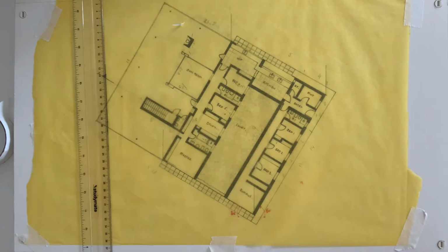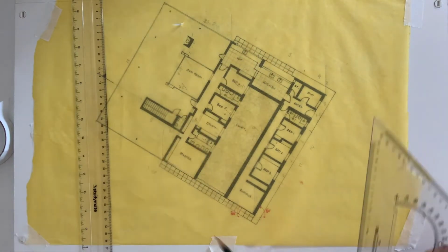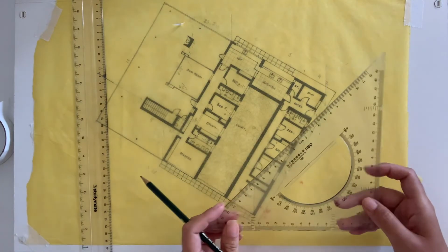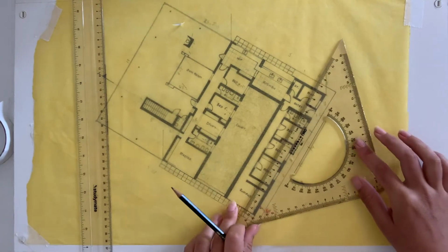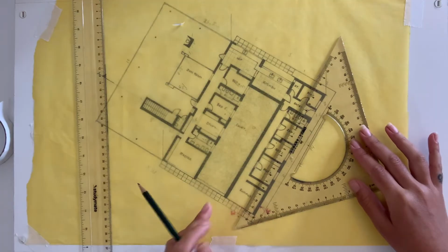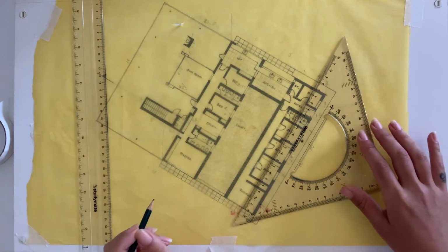Finally, after projecting all of the vertical lines, you will need to join the vertical lines at either 30, 45 or 60 degrees, depending on the choice of axonometric. When you start to join these vertical lines, it creates another plane in the drawing. You can do this quite simply by lining up a ruler and simply joining the lines this way.